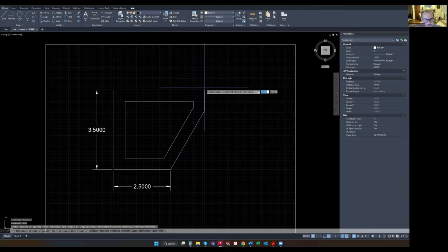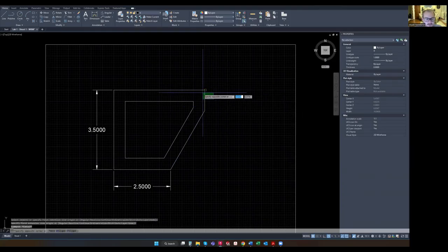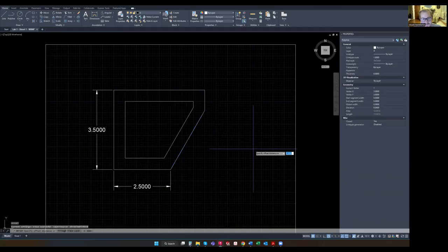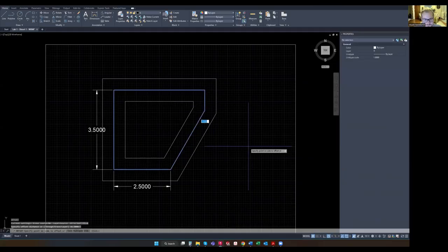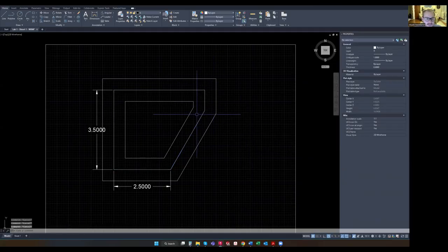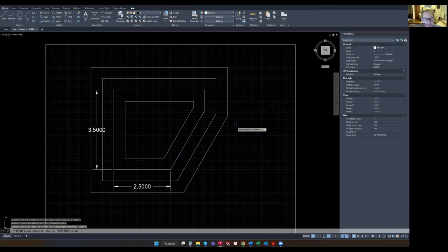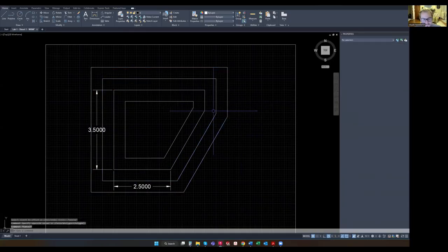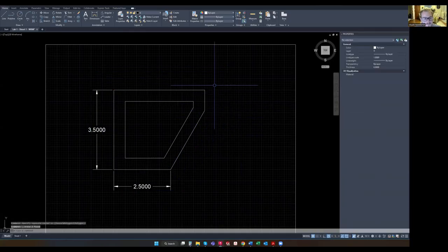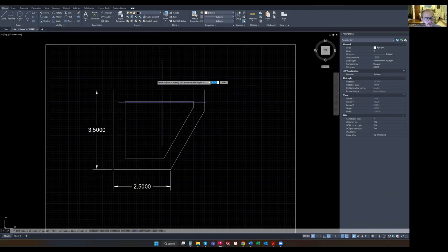in my dimension tool. And it's the same thing as if we did an offset. So if I offset this towards the outside and I click escape, if I click space bar, the offset command is the command that comes up, not the dimension tool. So just kind of a fun fact. So let's go back into our dimension tool. Remember, now I played around with the offset tool, I had to go click the dimension tool again.